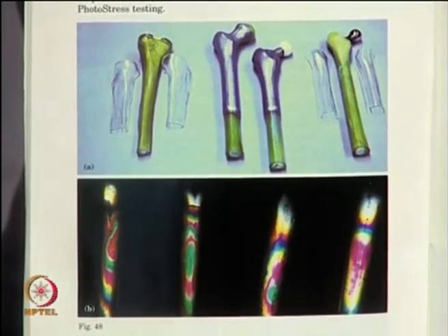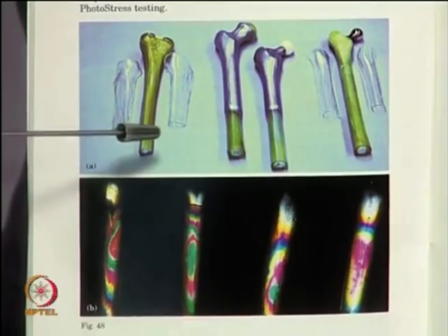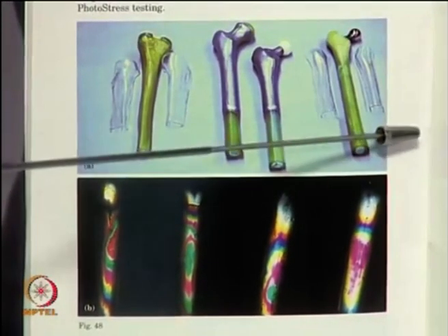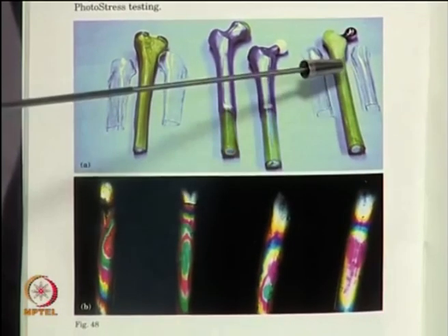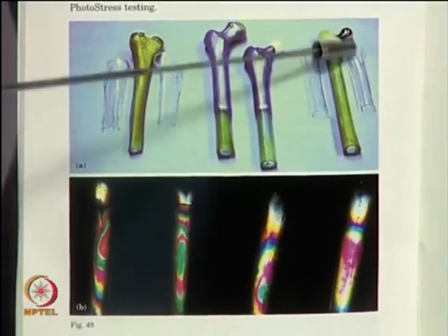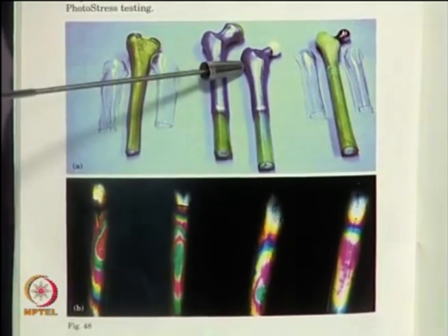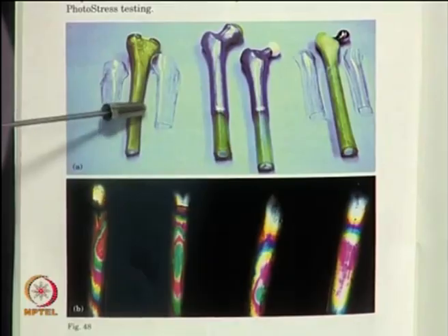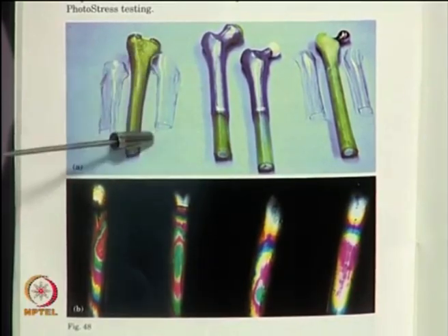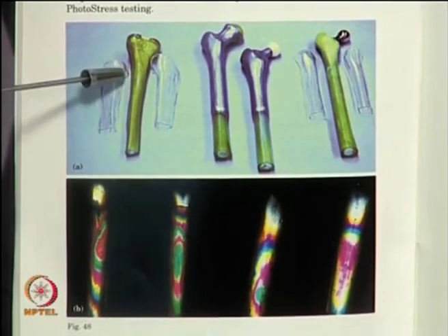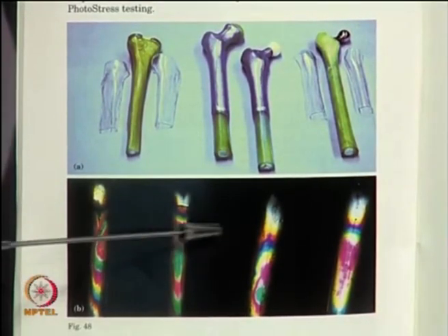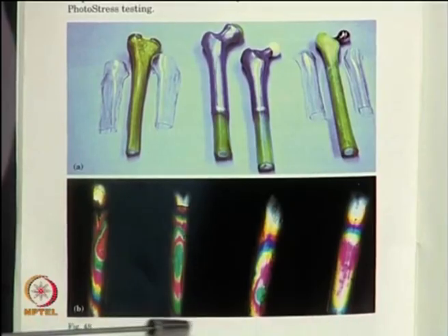This shows another example of application of photoelastic coating, and here it is for prosthesis example, where you have hip replacement and you want to analyze what is the influence of these implants. You have a shell which is made by contourable plastic, which is bonded onto the bone, and these are all the respective fringe patterns obtained for various configurations.